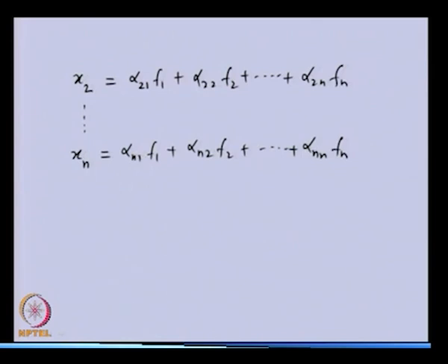In general, we will see that in this particular case the influence coefficients will have this property: cross-coupled terms will be the same, and we can obtain these by the usual deflection relations of the bending of beams, which we have studied in strength of materials. So, let us see the definition of the influence coefficient alpha ij.